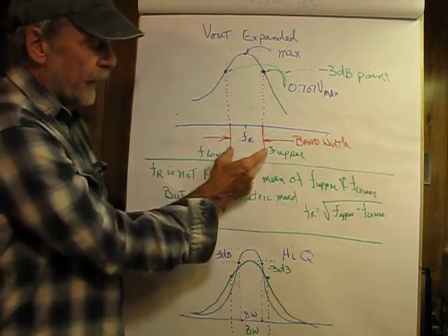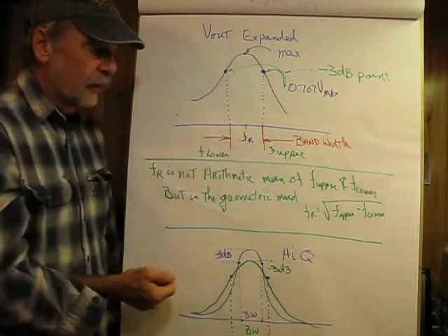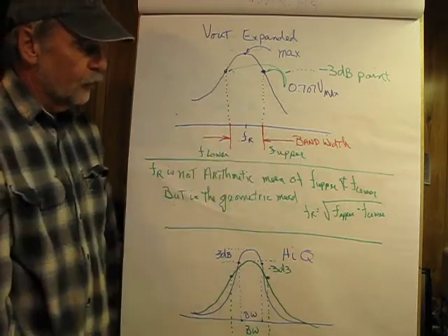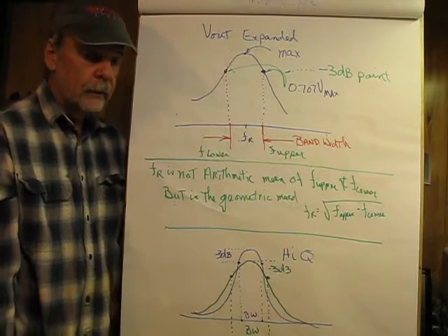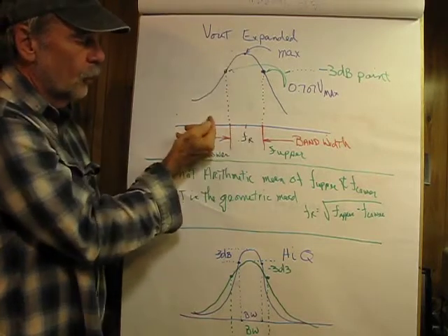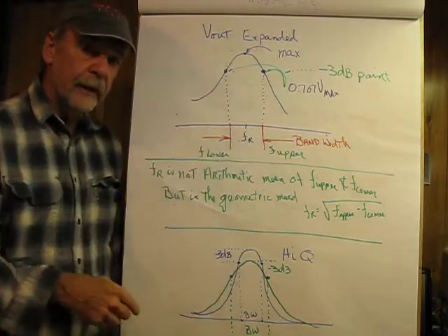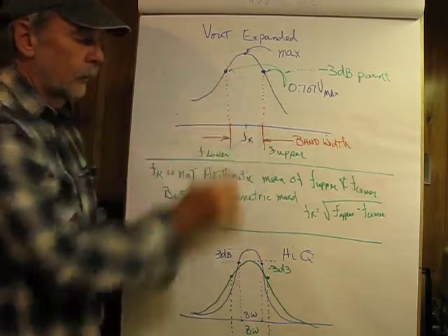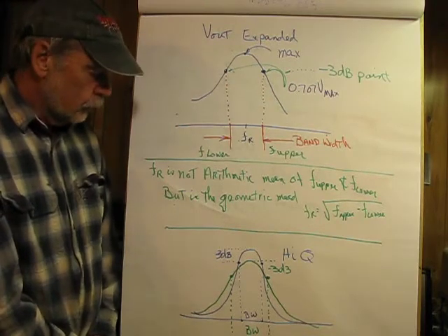So what we see is that from one side to the other would be the bandwidth, with FR sitting sort of in the middle. And if we'd like to think about a useful use for this circuit, it would be tuning in a radio station. Suppose we have 1220 here, and we want to select him and listen to him, and 1100 is here and 1300 is here. The output voltages of these two guys are going to be discriminated against by the resonant circuit. Hence, it would let our 1220 come through much more strongly than the other two signals.